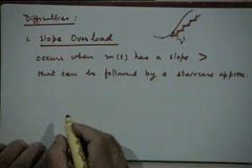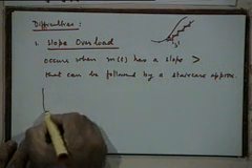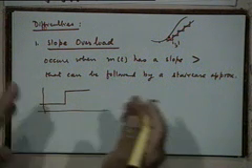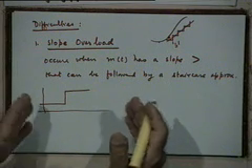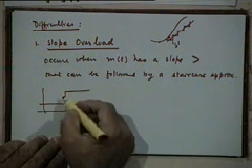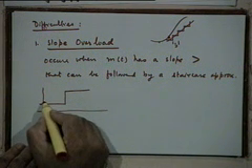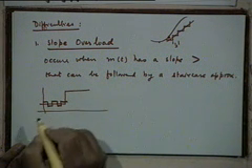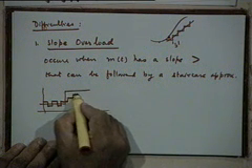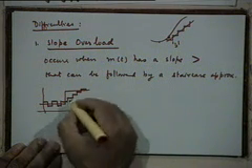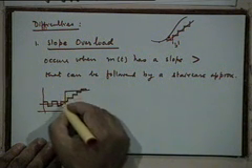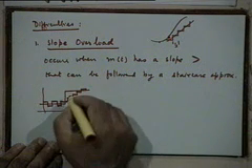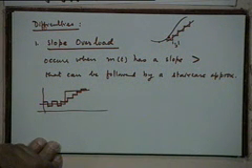As a worst case picture of this, suppose your message signal suddenly is a step function, a worst kind of situation. There is infinite slope here, right? So your staircase approximation was going perhaps like that, right, and beyond this it can only go like that. So you have totally missed this step. You can only go like a ramp, you cannot go like a step, right?